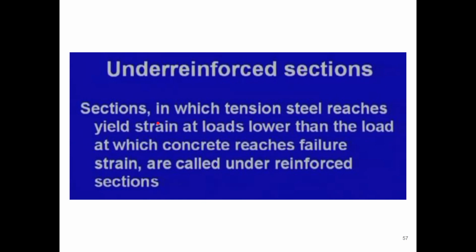In case of an under-reinforced section, these are sections in which the tensile steel reaches the yield strain at loads lower than the load at which concrete reaches failure strain. Those are called under-reinforced sections.